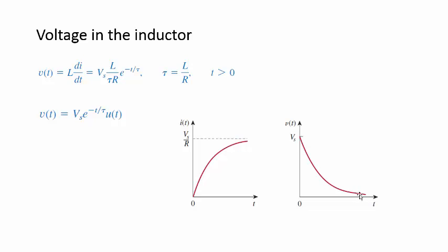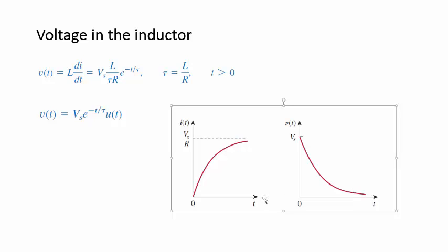I don't know why your textbook didn't mention it, but a similar thing occurs for the capacitor circuit. While the voltage charges up across a capacitor when you close the switch, at the same time the current will be dropping less and less until after a long time the capacitor is like an open circuit, which is no current at all. So when you look at the voltage and current relationships for the RC and RL circuit, they are complementary to each other.